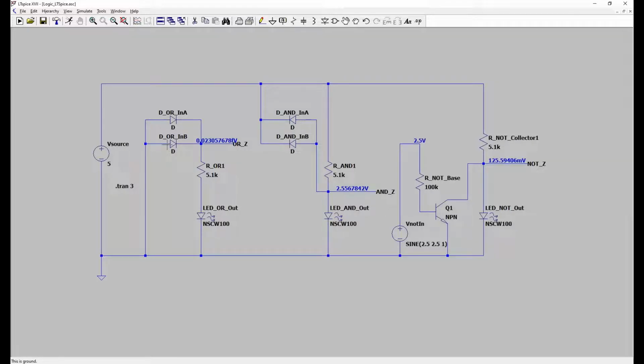But what I'm thinking is that if I set up two sine waves that are 90 degrees out of phase, I would get essentially a quadrature encoder input that would cover low, low, low, high, high, high, high, low, back to low, low on a 1 Hertz cycle. So let's try that.